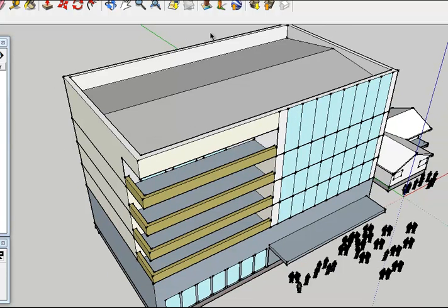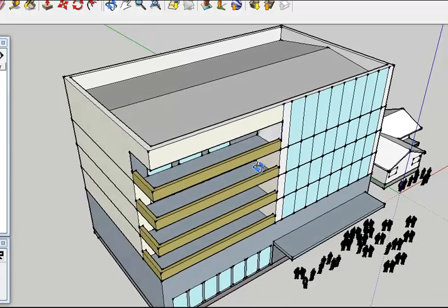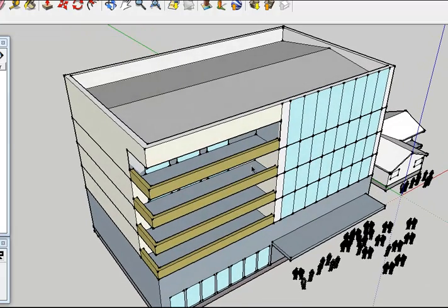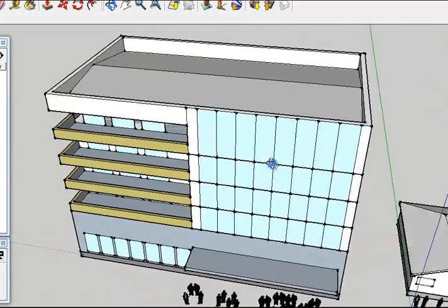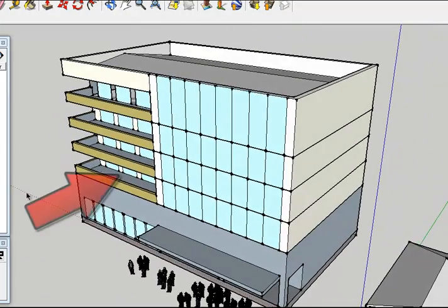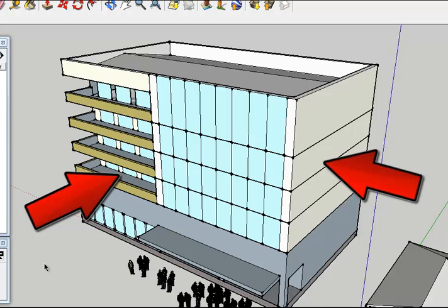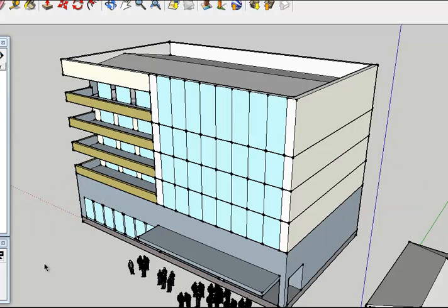So in terms of the roof area, the rainwater that can be collected, and also snow loads can add a significant amount of vertical load to a building as well. If you think about the size of the building here, it's subject to more loads from earthquakes and wind. So you can appreciate that a building like this, as it gets bigger and bigger and bigger, it just catches the wind like a sail, and the bigger the sail, the faster the boat goes. Hopefully our buildings stay in one place. The point is that the wind loads and earthquake loads increase on a building as its size increases.